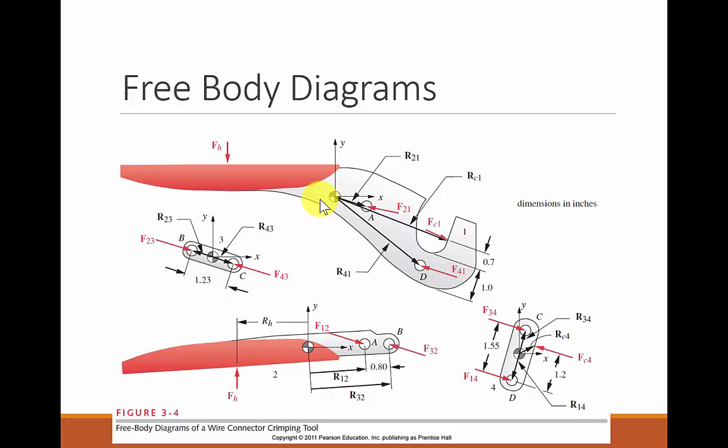And now, how many equations of motion do we have in this problem? So each body has 3 equations of motion. So F equals ma for each of the bodies. So that means there are a total of 12 equations that we have to govern. And this is again taking the understanding that we're in the plane.